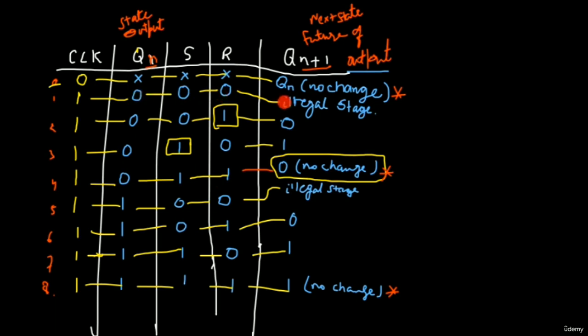And when will it change? Well, in the third one, if you look closely, you set but you don't reset, so it changes, it inverts the Qn here from 0 to 1. And in the same way, if you reset everything, it will restart the game again. If you're playing a video game, you will understand it very clearly, you can relate to it. So it's going to change. Now if you set but don't reset, remember I am using negation like not, don't for the zeros, and yes for change, that's 1.